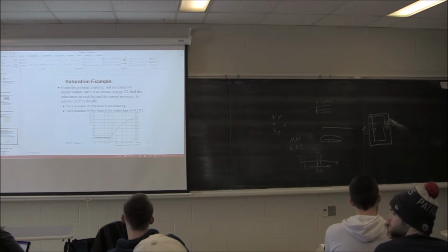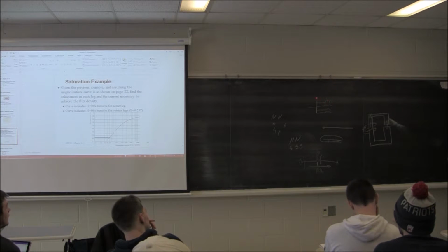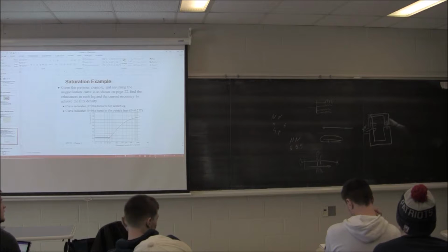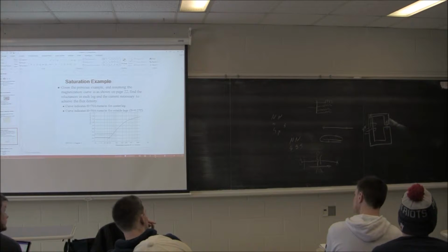Can you balance it out later down the line? You can boost the voltage because all this is really going to do is knock down the fault current, but it also decreases the voltage. So usually what happens is you run your system voltage a little higher than nominal, and then that way you can account for any voltage drops in those inductors.